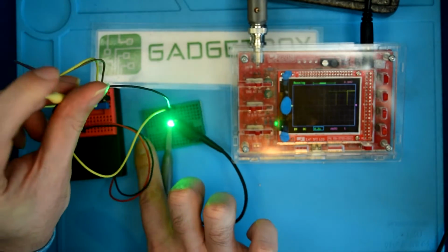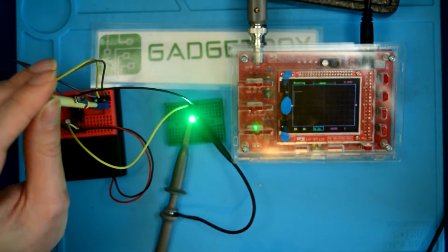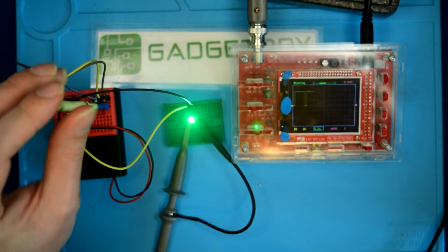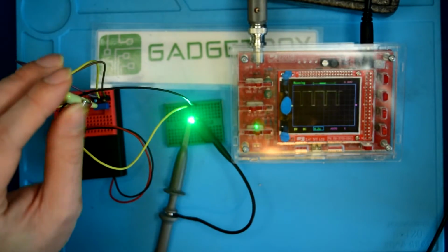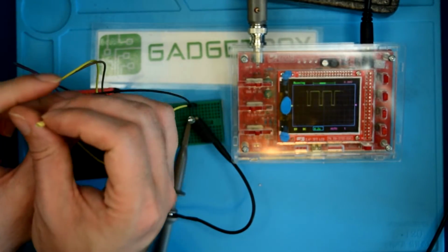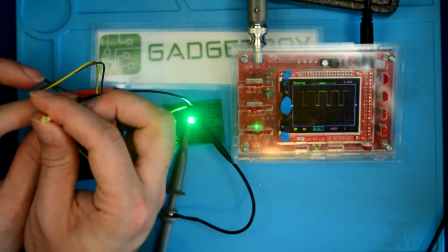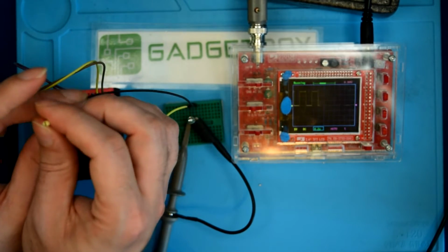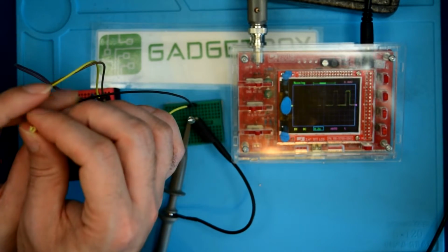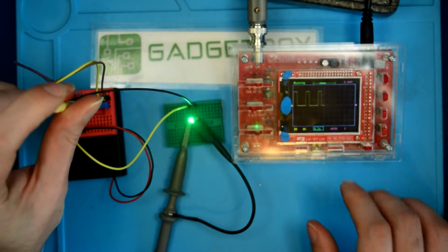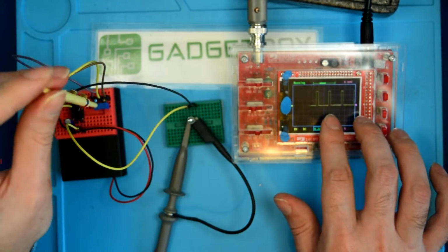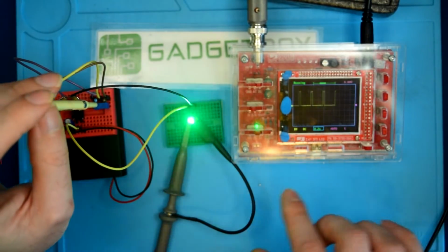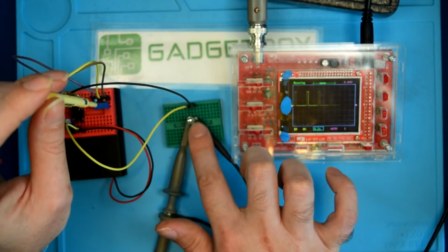I want to cover up the LEDs so you guys can see what's going on. I probably should have done some sort of flashing light warning for this, but maybe next time. Anyway, so let's go in the opposite direction. Let's reduce our duty cycle. Probably should have used a coarser potentiometer for this, but whatever. Anyway, so now as we're going further down, you can see the pulse width modulation. Now it's spending a lot of time off as opposed to on, and you can visually see that here.